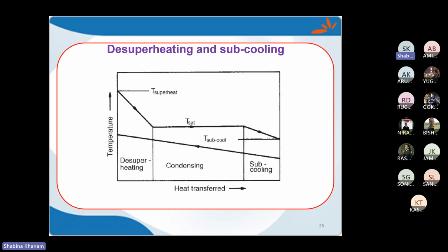What does it mean? If sufficient de-superheating we are considering, what is the meaning of that sufficient, that we will discuss. Okay, so if the degree of superheat is large, then for this case and for this case, heat transfer coefficient will be calculated differently, because in this case the mean temperature difference would be based on this and this. Okay, so that would be LMTD into FT. In this case, it would be LMTD only.